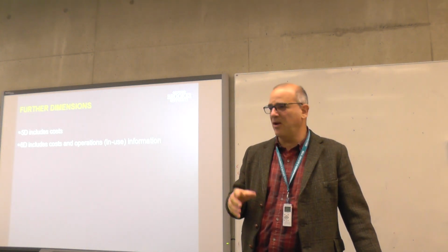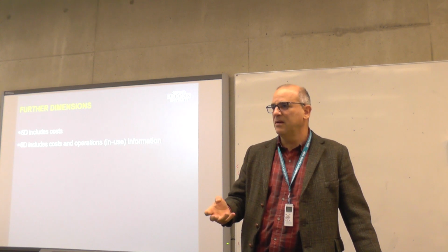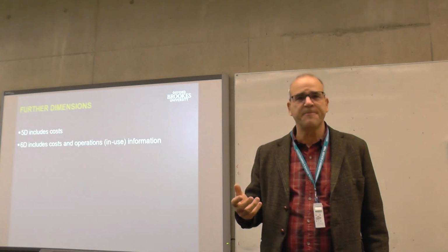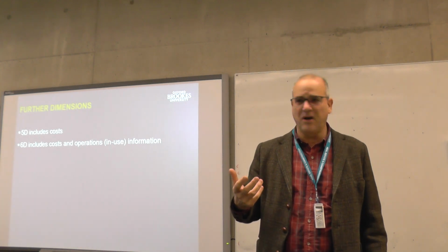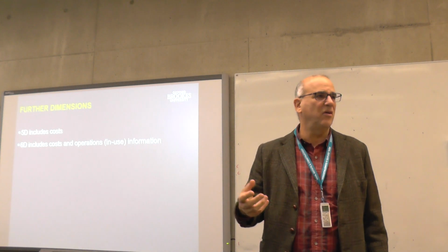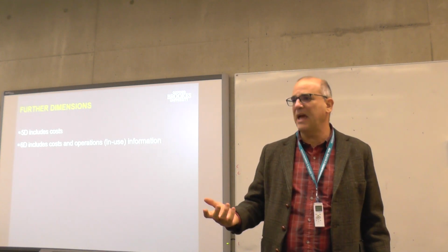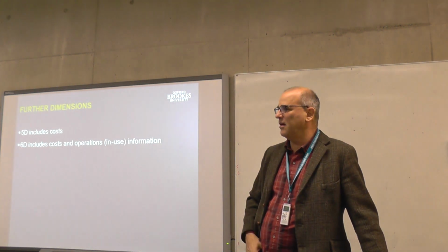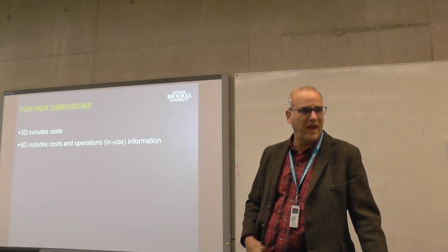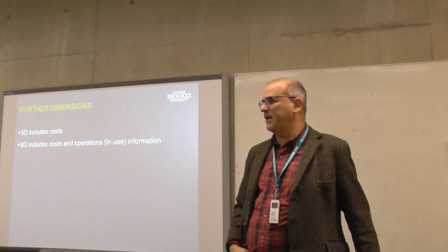It'd be very nice to go back to the BIM model, run some tests, investigate some things, and come up with a solution. Maybe it would be installing an additional vent, or increasing the size of the vent, or changing the way the intake louvers are structured.